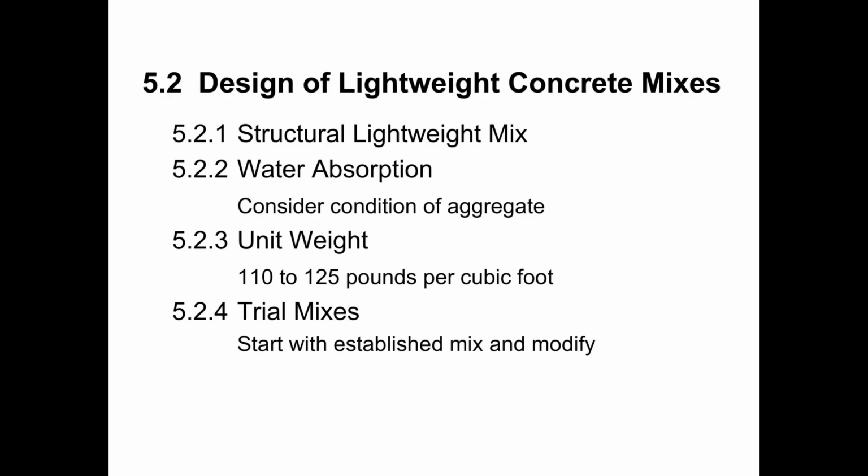Even with taking these steps, there's going to be some variation in the moisture condition of the aggregate, not just from day to day, but also from batch to batch. And so very tight controls on batching need to be employed to ensure that we get a consistent mix from one batch to the next.